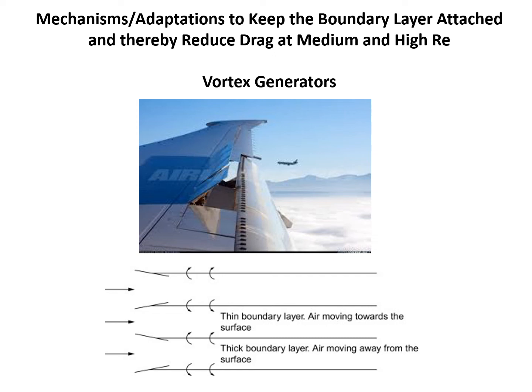These are actually called vortex generators. You're seeing them on the edge of this airplane wing. If you've flown, when you look out the airplane window, you've almost certainly seen these on the wings. And so basically it's preventing or reducing the point of detachment of the boundary layer.